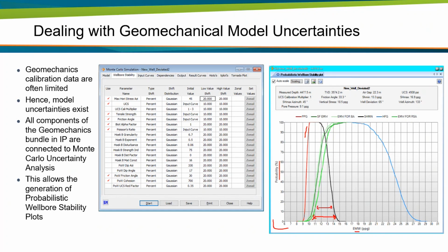at the low probabilities. What does that mean? Here, 20% would mean that if you drill with these mud weights here, you have 20% probability that you drill without issues. So if you would drill with 12.5 ppg, you pretty much reach the maximum probability of drilling without issues of somewhere 60, around 70%, but that might be too low for you, right?